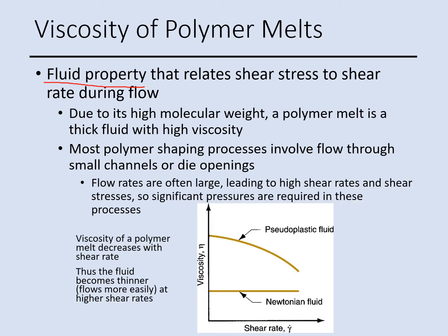Viscosity is a fluid property of a polymer, and that is related to shear stress and shear rate during flow. When the polymer melts, because of its high molecular weight, it becomes a very thick fluid. Thick fluid means high viscosity.